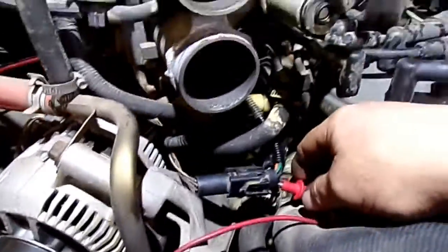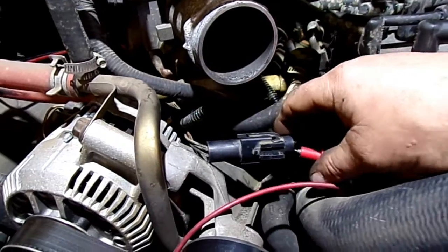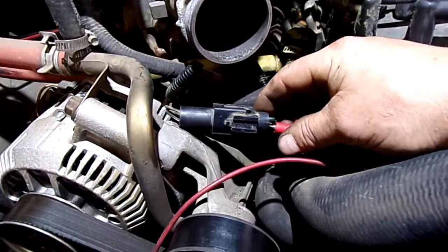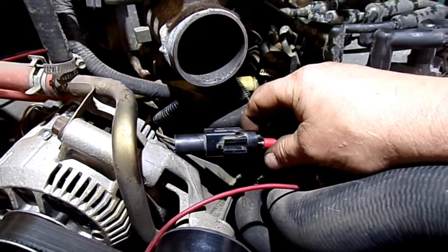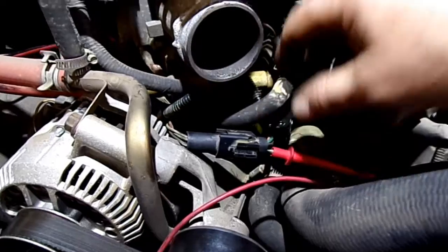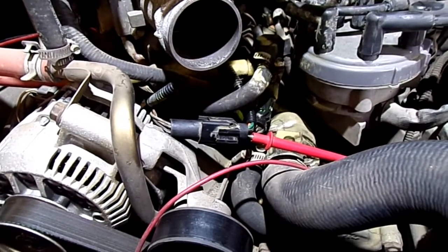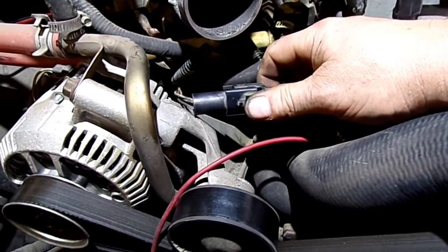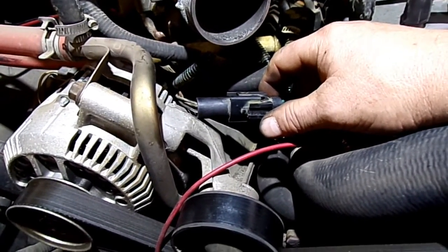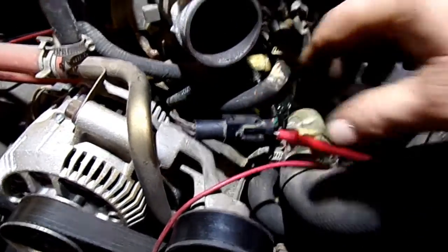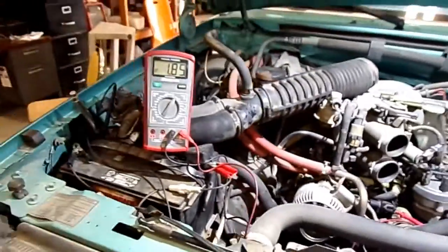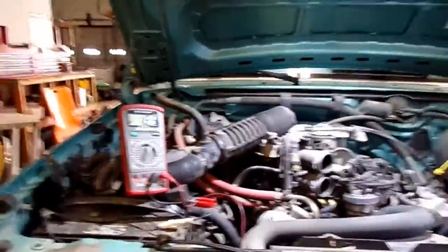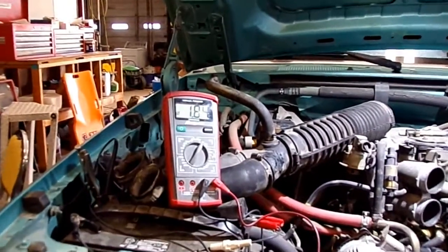I've got this throttle position sensor connector down here that I'm back probing, and I was back probing the voltage reference, and I wasn't getting any voltage reference, the 5 volt. I wiggled this connector and it seems like that 5 volt would come on and then go back off. I'll show you what I'm talking about.